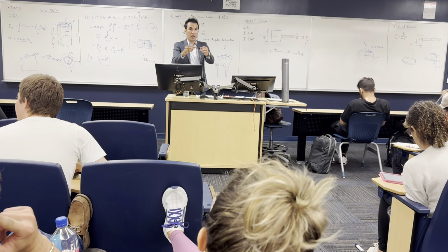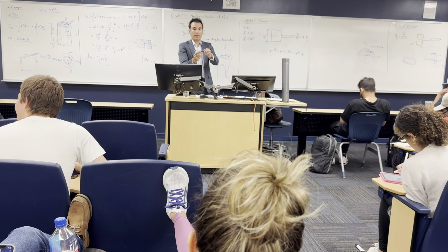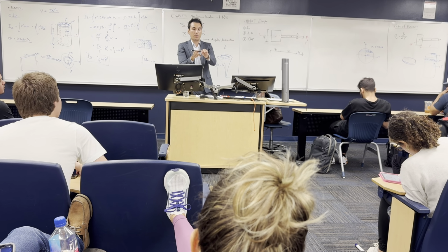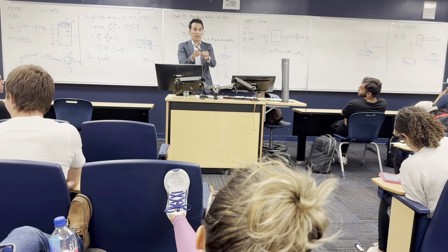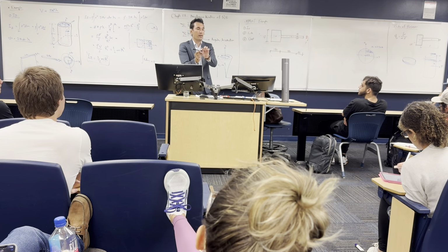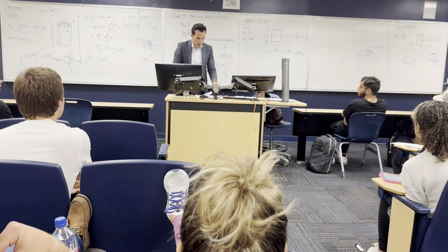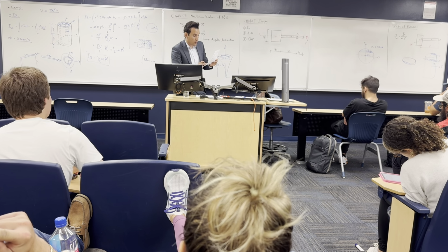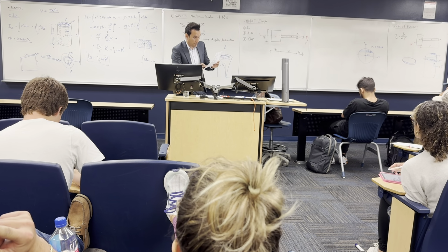So this is the bar that we have, for example, okay? And this bar, this is the CG, we are looking at the mass moment of inertia about an axis like this. I'm going to look at the mass moment of inertia at the CG, how it rotates this way, and then I'm going to look at how it rotates at a different point. So I'm looking at either this axis, right? Let's see what axis. It can be X, it can be Y. So as you see here, Ixx equals Iyy equals 1 over 12 ML squared. Okay?